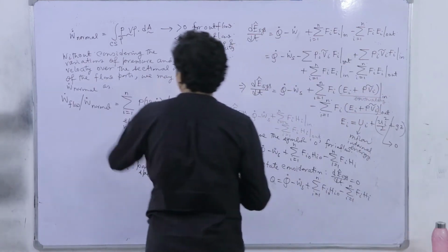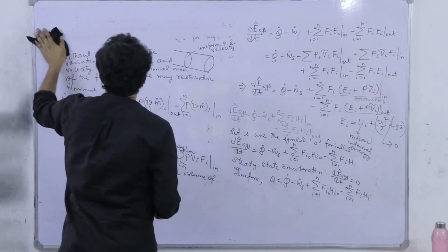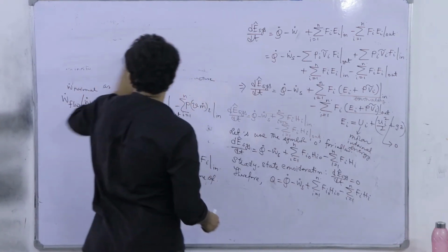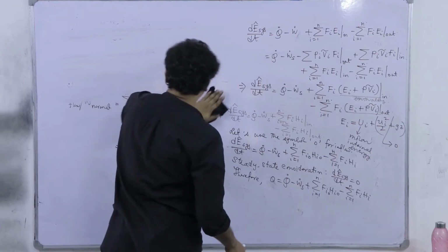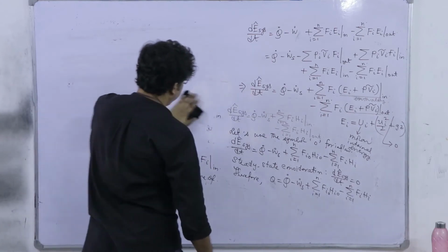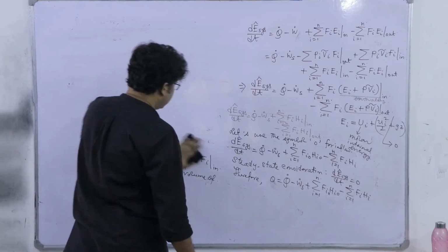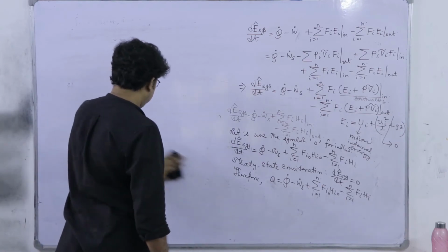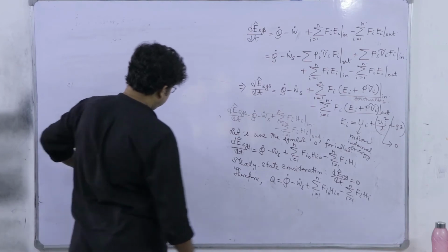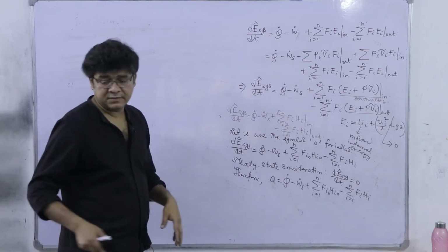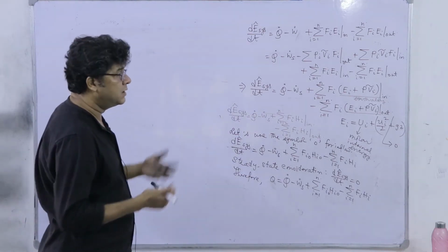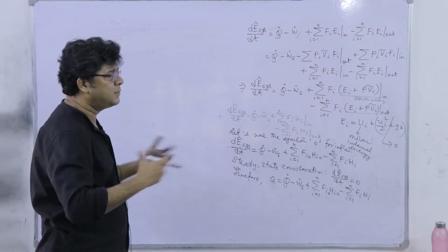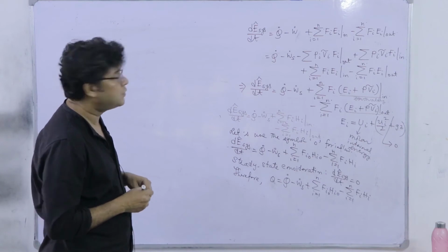Next we incorporate the reaction. Right. How can we incorporate the reaction? Through this enthalpy term. Definitely the heat of the reaction, the thermal effect of the reaction, affects the thermal state of the system through the liberated heat, right? And additionally through the enthalpy of these incoming and outgoing streams.